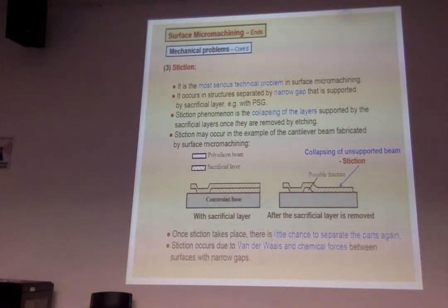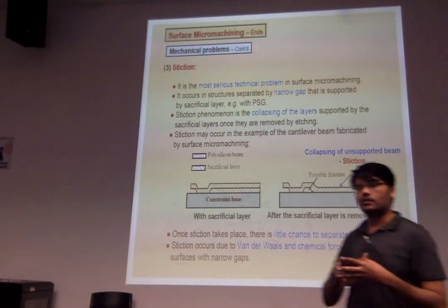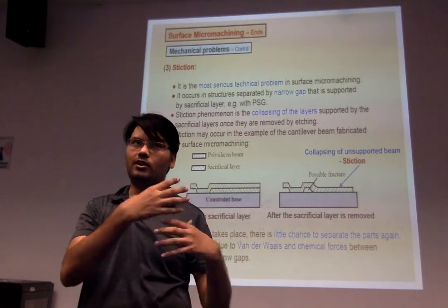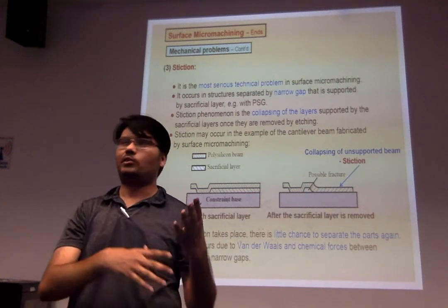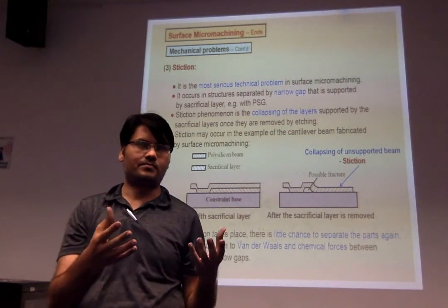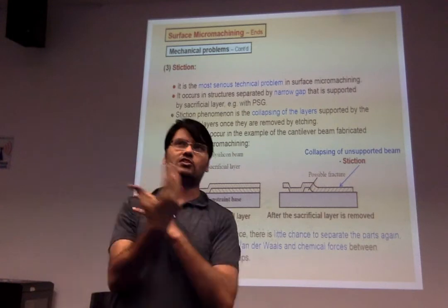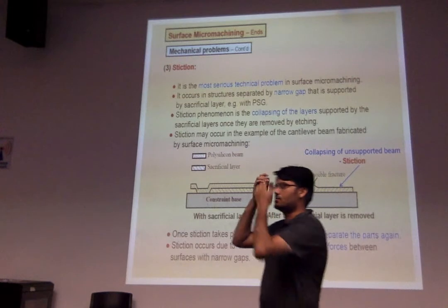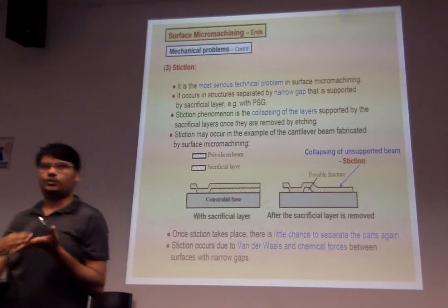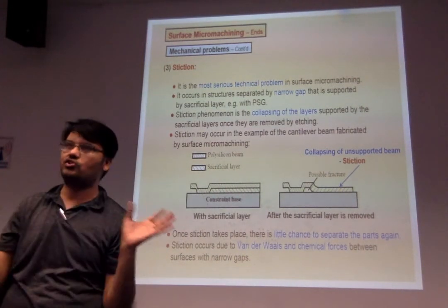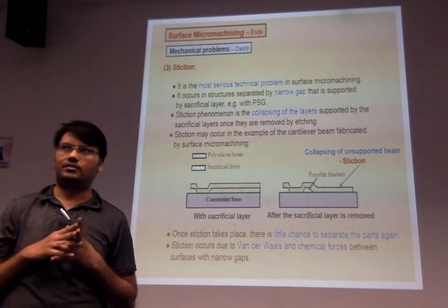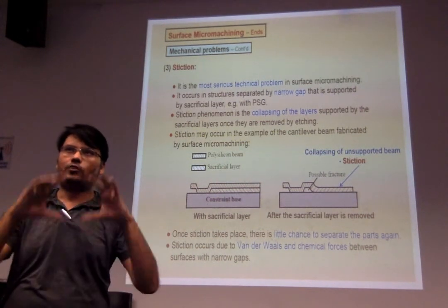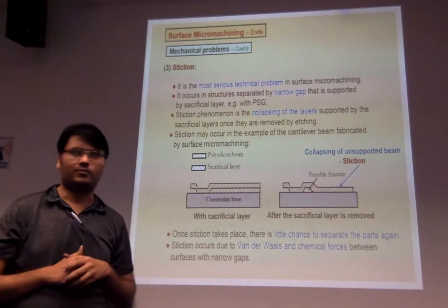Okay, the next one is about micro-manufacturing processes. In the previous weeks it was fabrication techniques, such as deposition and etching. Now we are talking about making a three-dimensional structure, since MEMS devices are mostly three-dimensional. How can these techniques be combined together? The first one was bulk micromachining, which is only etching, just through etching, how three-dimensional shapes are made. The second one is adding things one on the other, layer by layer, to form the three-dimensional structure, which is surface micromachining.